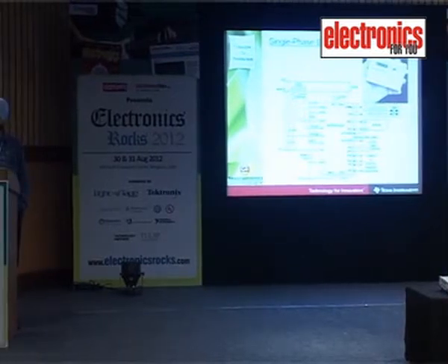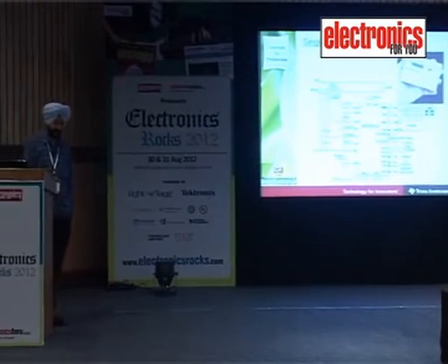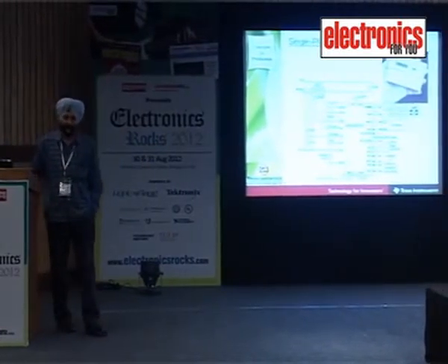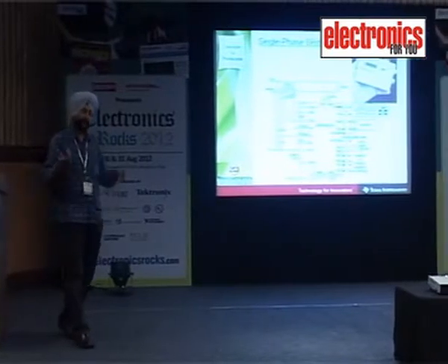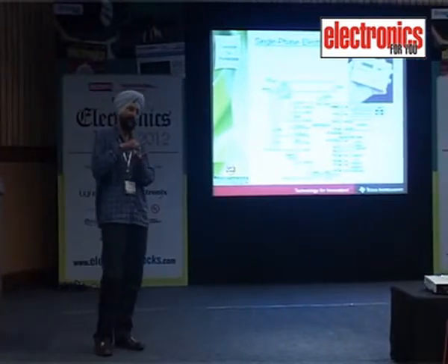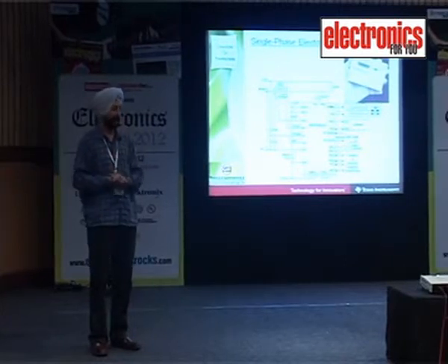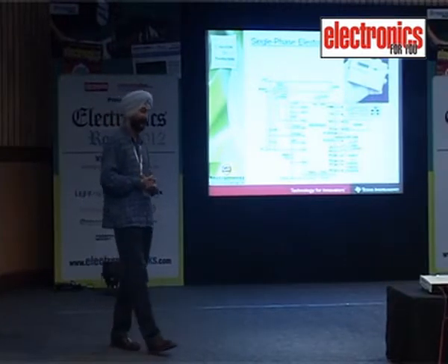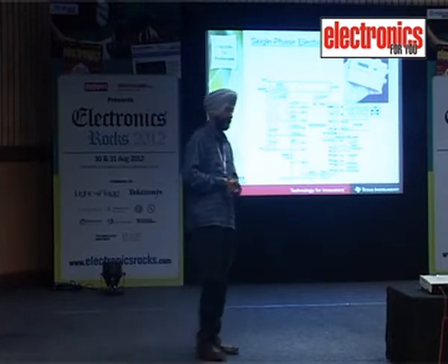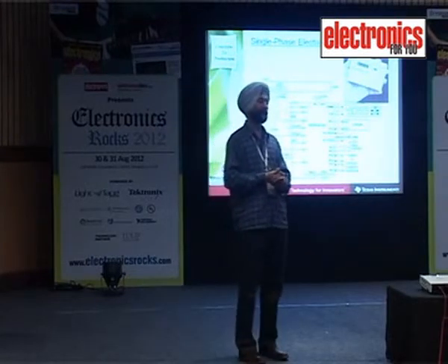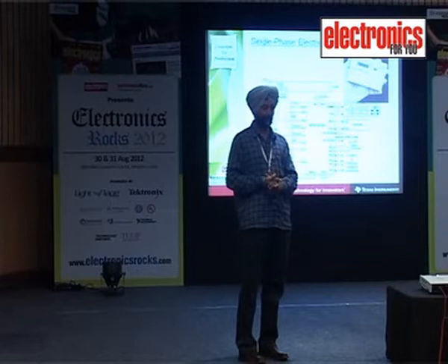Because the energy meter has a lot of challenges, especially theft and tampering. Sometimes people change the wiring or do something so that your chipset is not getting power at all. If the chipset is not getting power, then definitely you have a big challenge. It will not be able to sense anything, whether tampering is happening or not.